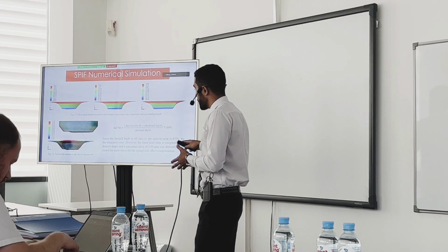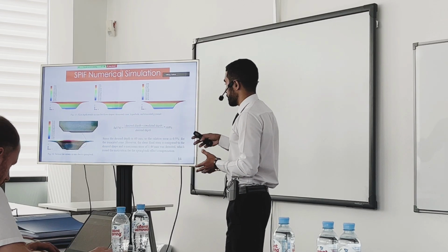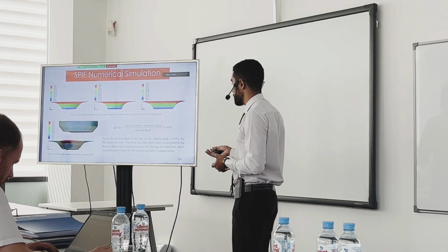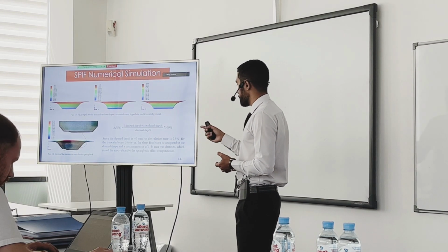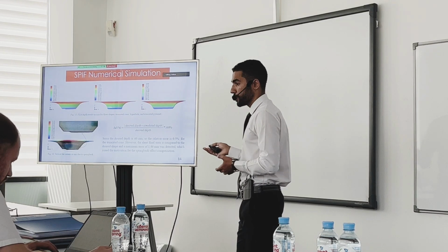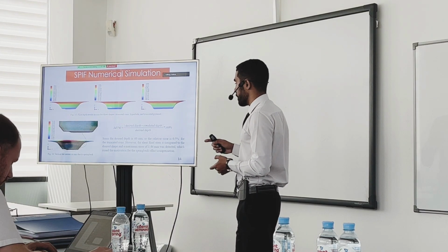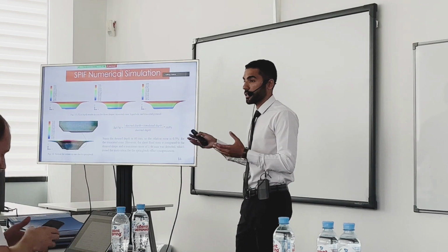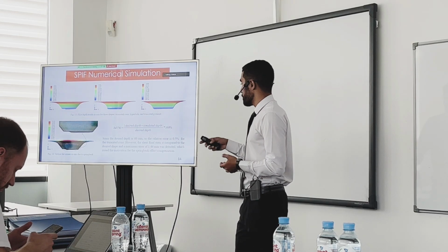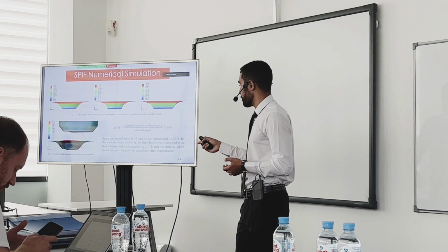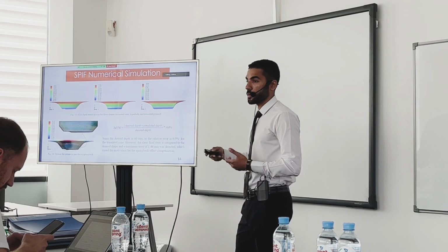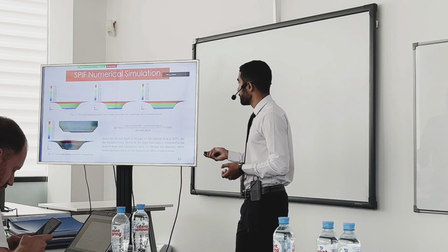At that point, I used an evaluation metric, the relative error between the desired depths and the simulated depths. And for example, for the truncated cone, the relative error was 0.5%. However, when comparing point by point the desired shape and the obtained shape, there was a maximum error of 1.4 millimeters, which raises the motivation to do the spring back effect compensation.